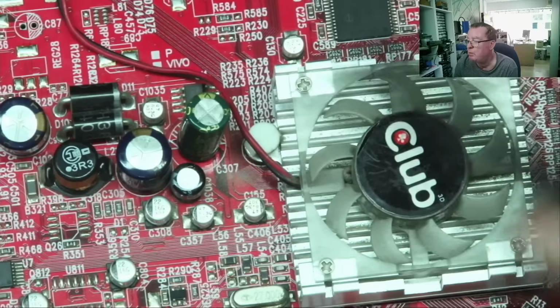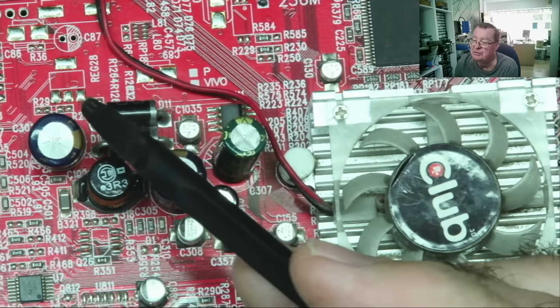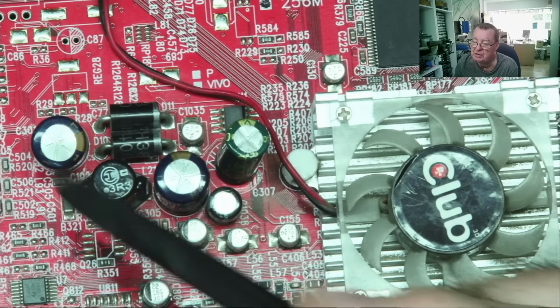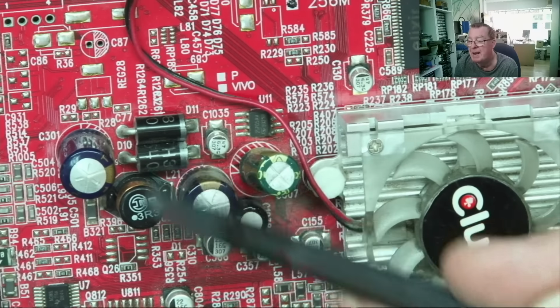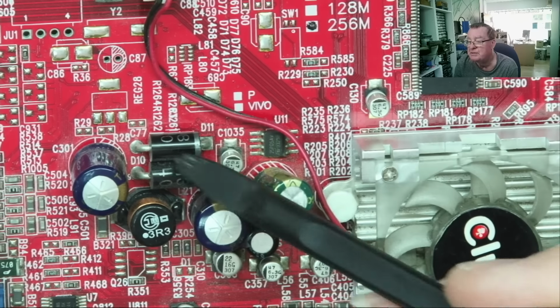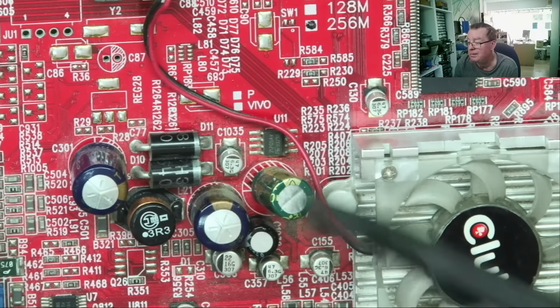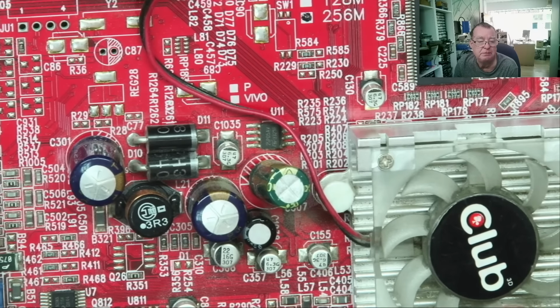That's drawing quite a lot of current. And these capacitors are running at high frequency. So this circuit is switching hundreds of kilohertz, maybe into megahertz. So these capacitors are just smoothing the output of this. There's the rectifier diodes, probably. And they run at high frequency, and these are more prone to failure.